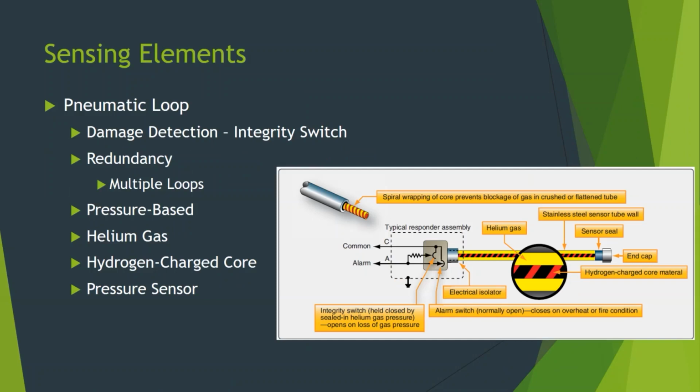Under normal circumstances, there's always a low current flowing through that resistor. If all of a sudden the current stops flowing, that's a signal that the gas pressure has been lost altogether. And now the indication computer, the indication logic circuits, will provide a caution that the fire loop's no longer working. So that's part of the design. It needs to be robust, and it needs to be able to indicate if it can't indicate a fire or an overheat.